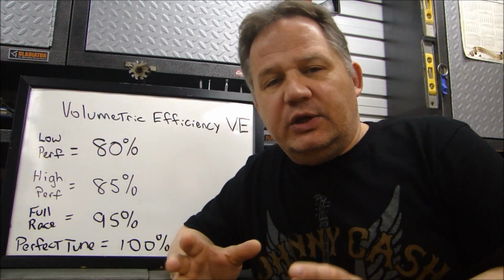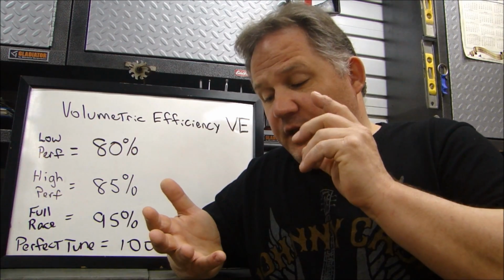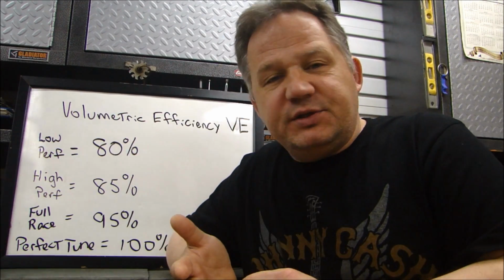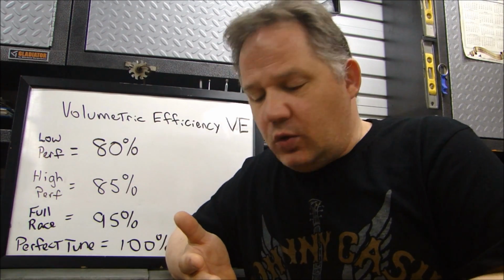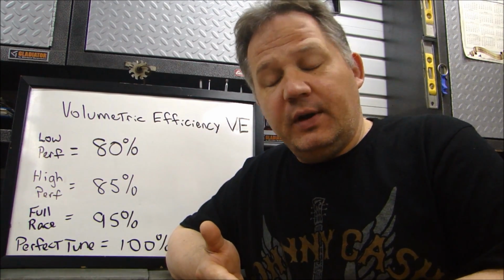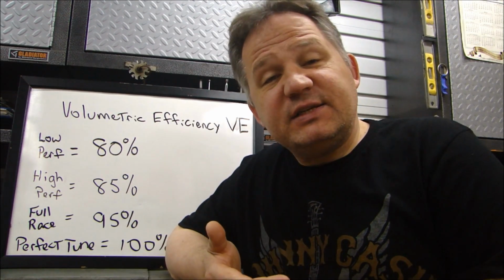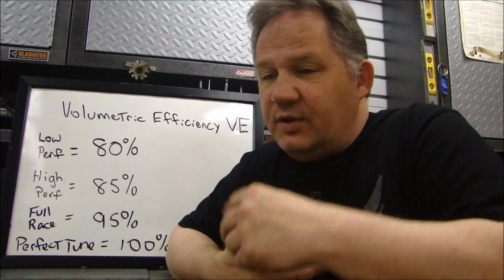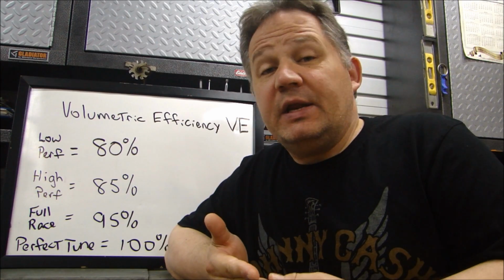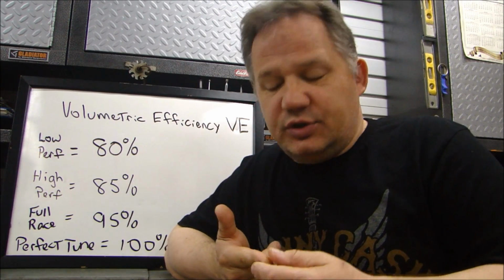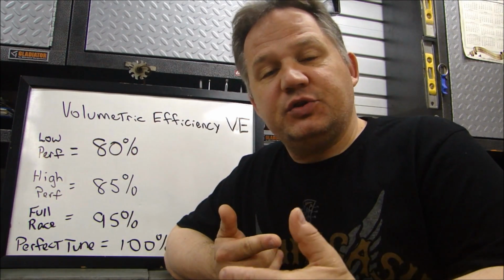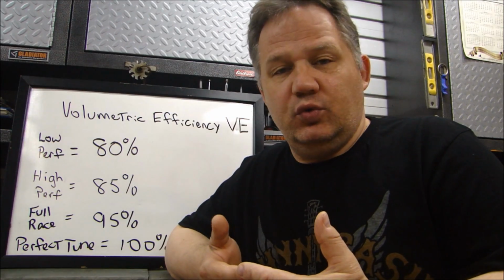A perfect tuned engine is one where the pistons, the rolling assembly, the pulse that's going to be generated through the compression ratio, the intake, how that wave, remember from the intake manifold video about theory, the pulse of the intake, the velocity of the fuel, the flow through the heads, how the flow is going to go through the cylinders, how that's going to be generated, the exhaust. If the exhaust is chosen, there's no restrictions. The length of the exhaust is chosen for the pulse wave of the exhaust, so it's perfectly tuned.